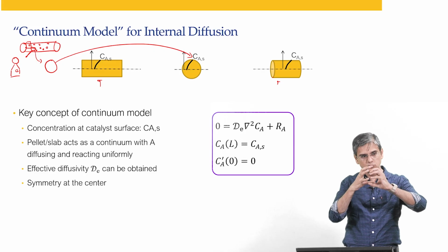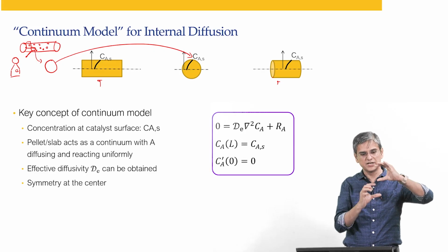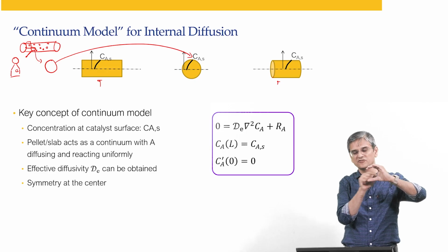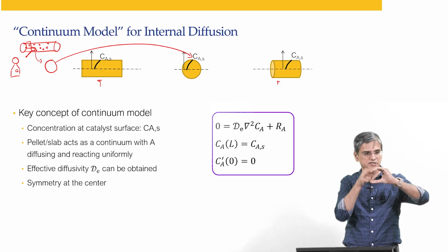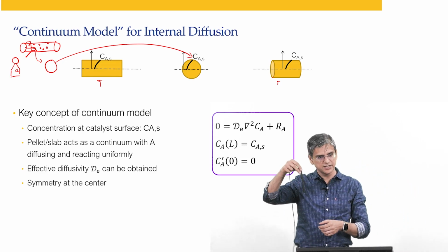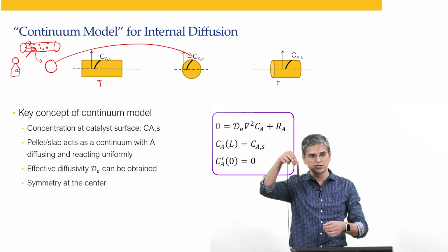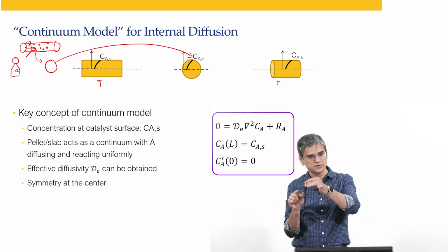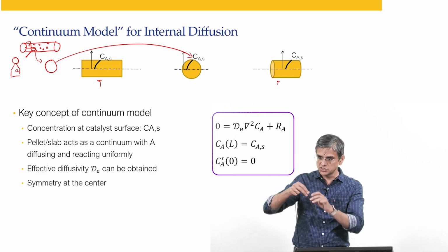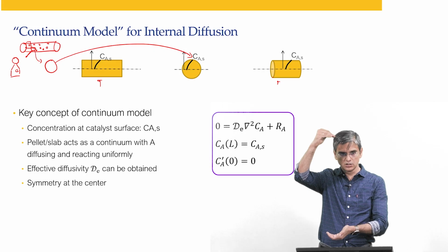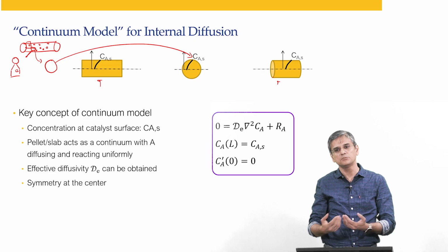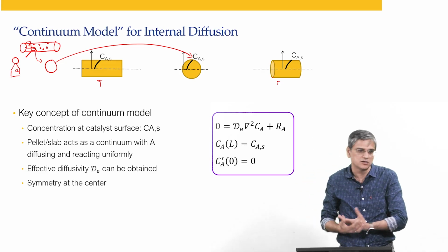So, if I were to use, let us say, a pellet closer to a cylinder like this, what is going to happen is a lot of heat transfer in this direction, but not enough heat transfer in this direction. The other option is to make a pellet like this. The problem with a cylindrical pellet like this might be a lot of heat transfer in this direction, but not much heat transfer up and down. If we wanted to use this, let us say if the reactor was this long, the entire cylinder had to be extruded to this length. The question is whether or not that material can handle that processing. If it cannot, then we will not do it.